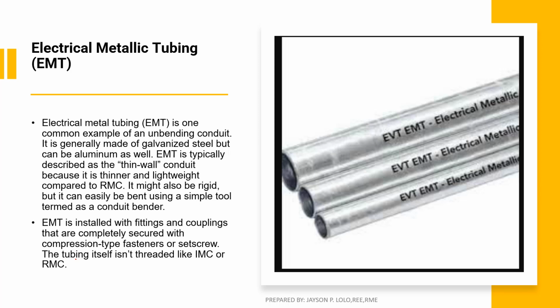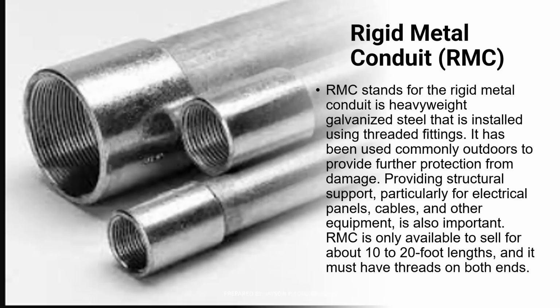Take note that the tubing itself isn't threaded like IMC or RMC. Based on the picture, there is no thread. The second one is the RMC. As you can see, there's already a thread, unlike the EMT.